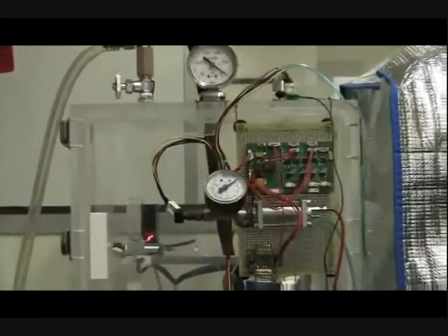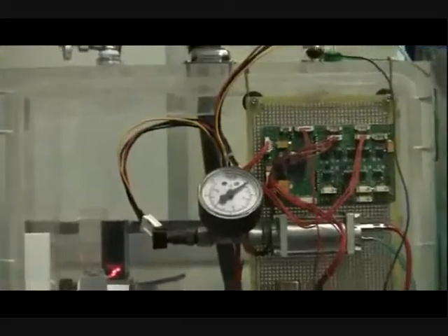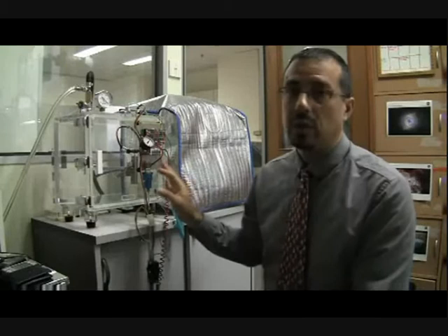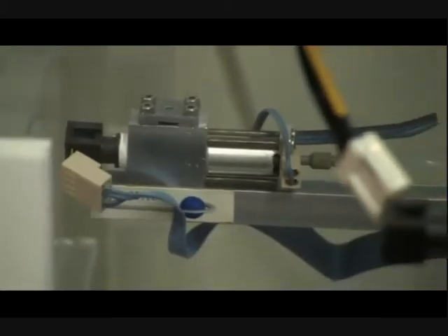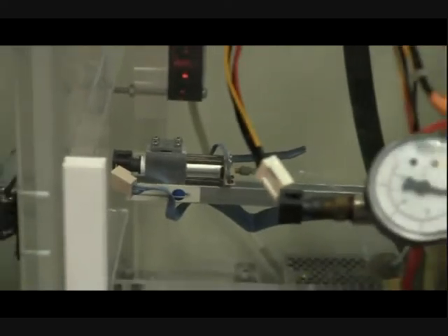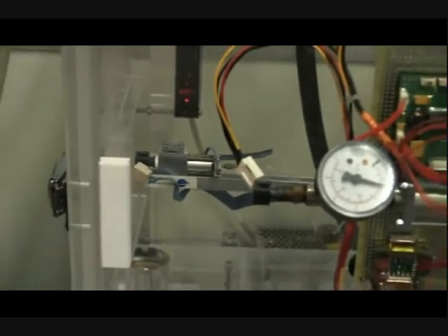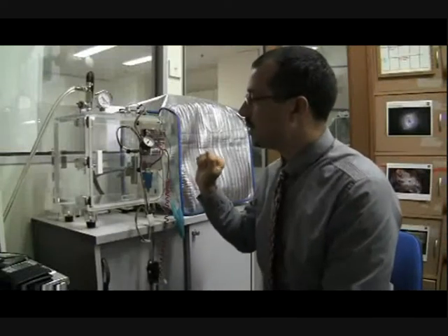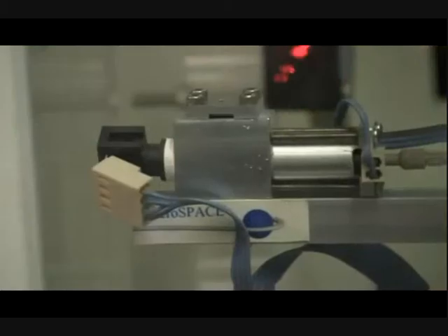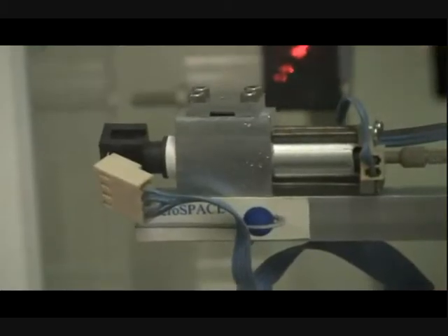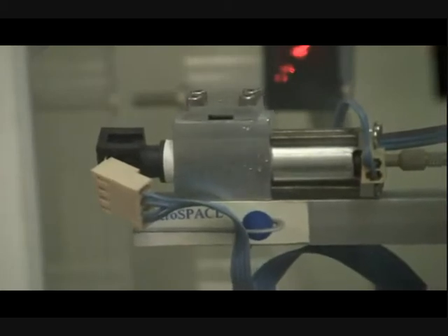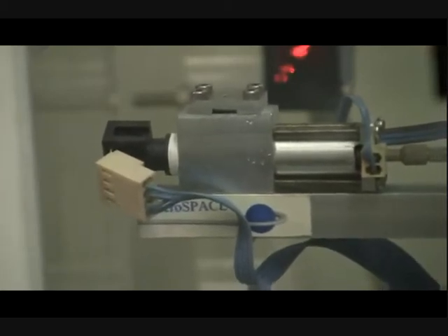This system we have invented and created particularly for our micro nozzles, and this is what we always use for R&D and for calibration of the nozzles. The function of this system is to recreate the vacuum environment that is in space, and to measure the force produced by the micro nozzle. When the nozzle is operated, the arm will swing, and the amplitude of the swing is proportional to the force, and we can measure this because we have a laser that is measuring the position of the arm.